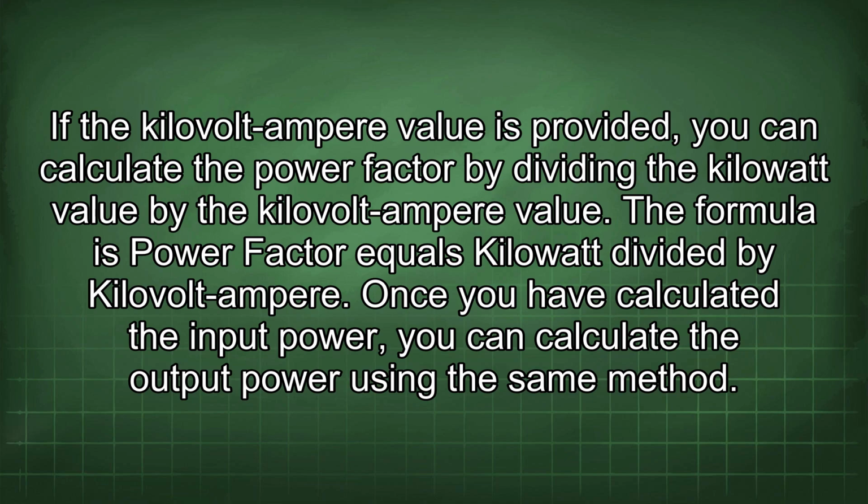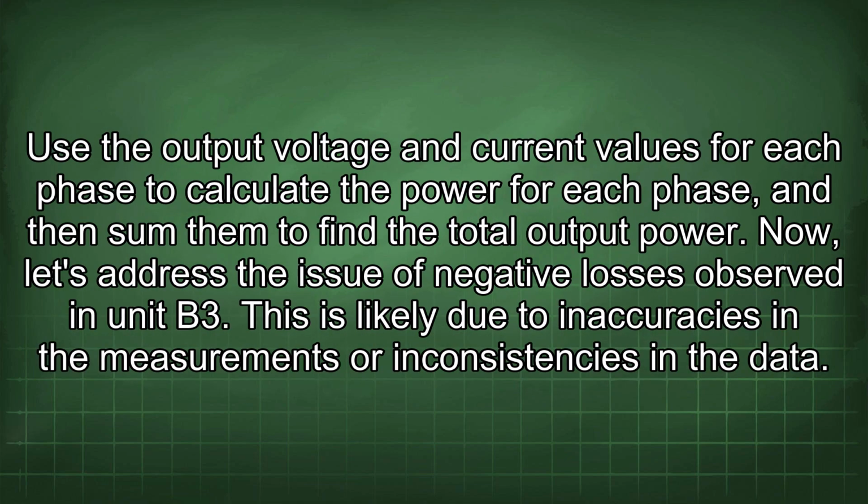Once you have calculated the input power, you can calculate the output power using the same method. Use the output voltage and current values for each phase to calculate the power for each phase, and then sum them to find the total output power.